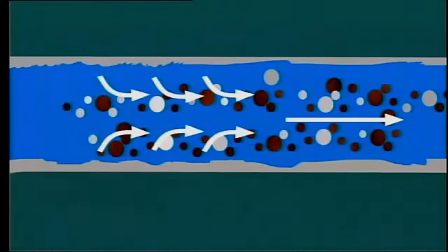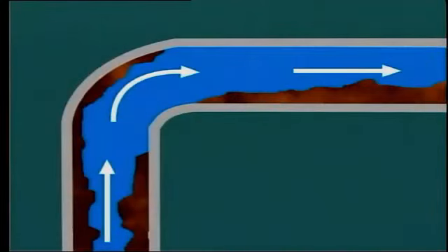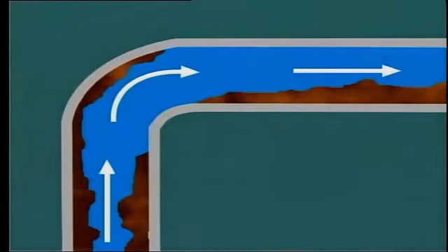The removed metal, products of corrosion, can also cause a problem, as this material now increases the total quantity of solids contained in the boiler water. As we know, this can increase the probability of deposits and scale formation on the inside wall of the tubes.